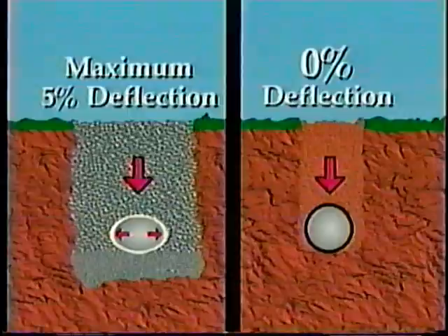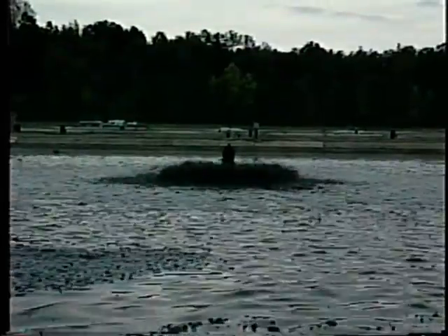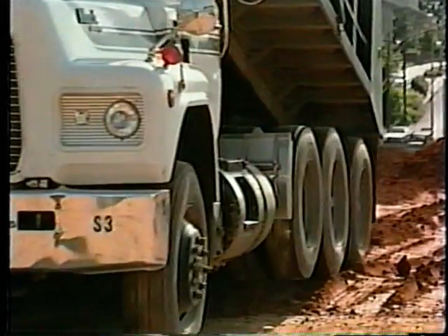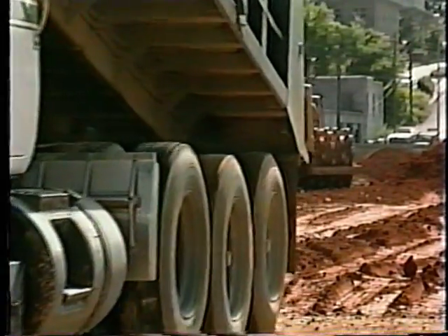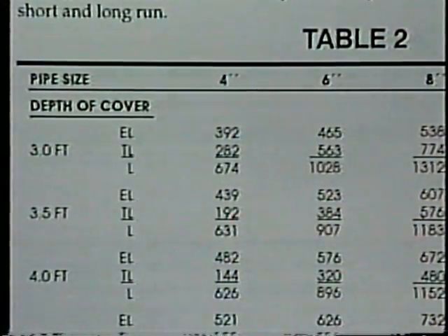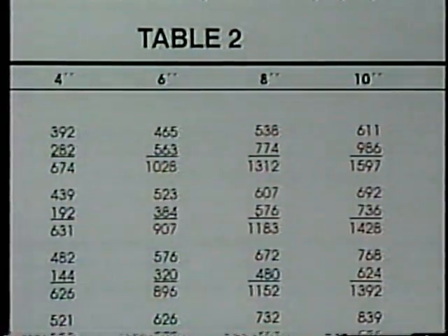Excessive deflection will result in infiltration of groundwater, overloading wastewater treatment plants, and exfiltration, contaminating the groundwater and soil. Another important consideration in underground piping installations is resistance to crush loads. Before selecting and installing piping materials, expected loads and crush values must be determined.